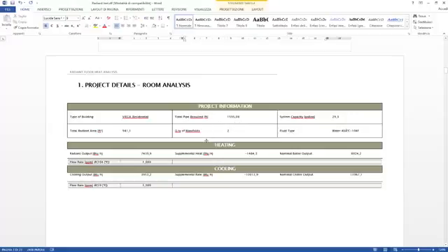1,595.08 feet. With our quantity of manifolds, we have 2. Our system capacity in gallons is 29.3, and our fluid type is water at a temperature of 40 degrees Celsius or 104 degrees Fahrenheit. For our heating, our radiant output in BTUs we have here, as well as our supplemental heat in BTUs per hour, our nominal boiler output, and finally our flow rate in gallons per minute. And we also have the same information for our cooling.